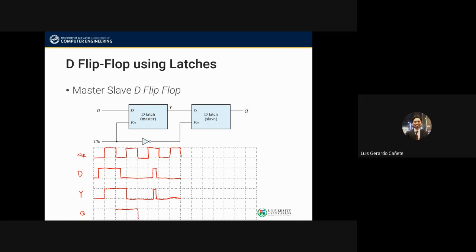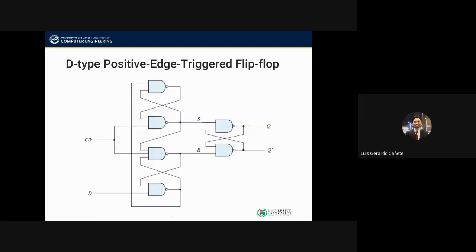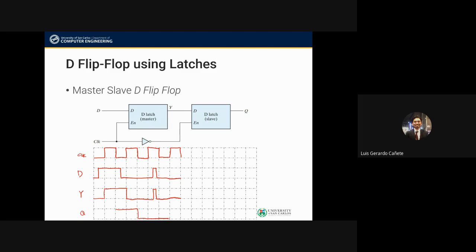And then we maintain that value. We disregard this value because we are high when this happens. So we copy this here because it's low. And then we just continue. Okay? So notice that now what's happening is we are actually responding to the changes only to clock. No, I mean, not changes to the clock inverse, but to clock itself for Q only when we have the negative edges or the falling edges.